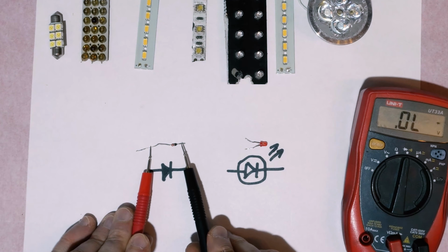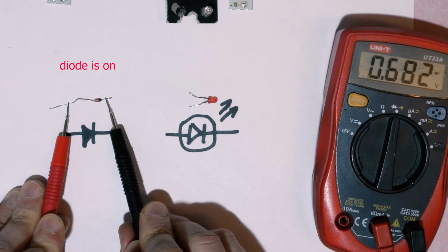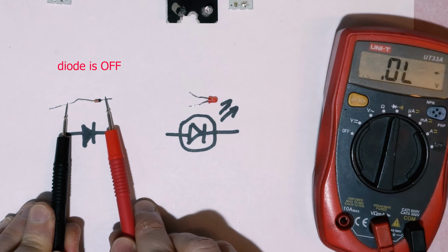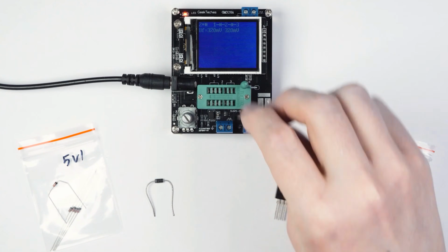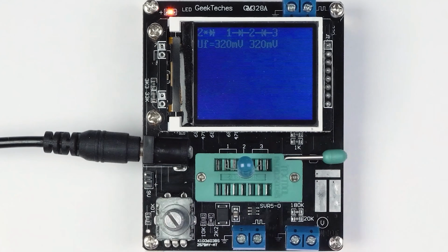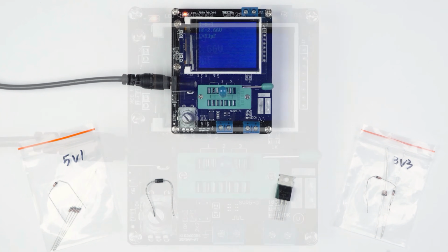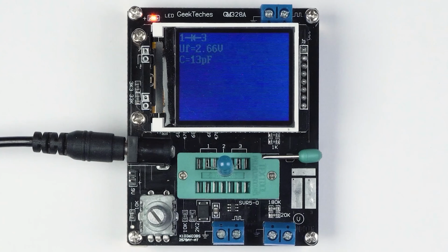So, to measure a diode, we must apply a multimeter's negative probe to the negative cathode mark. If we switch the probes, we can see no reading since the diode is off, or as they say, reverse biased, and current is not flowing. An LED is basically a fancy version of a regular diode, only as you pass current through it, it emits light. LEDs, however, usually exhibit a much larger voltage drop than regular diodes.